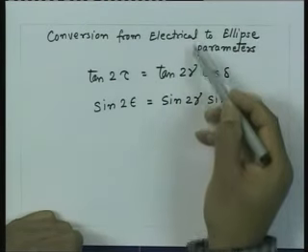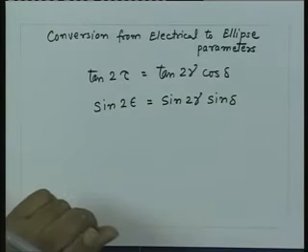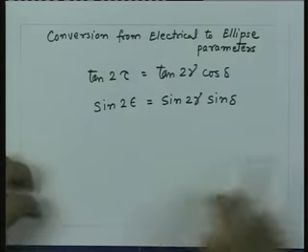So, if we are given the electrical parameters, that means if I know the amplitude ratio of the two fields which excite this electromagnetic wave, and the phase difference between these two electric fields, I can find the tilt angle and the axial ratio of that ellipse. As we mentioned last time, in practice we may have the opposite problem: we would like to generate a certain ellipse and want to know what the electrical parameters should be. So we also require a conversion from ellipse to electrical parameters.